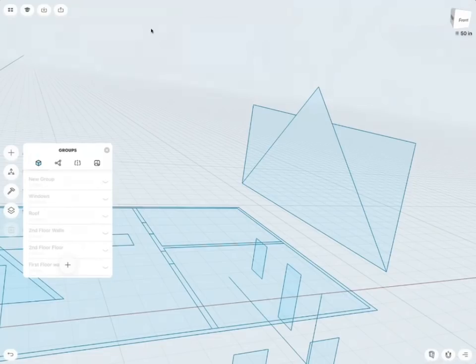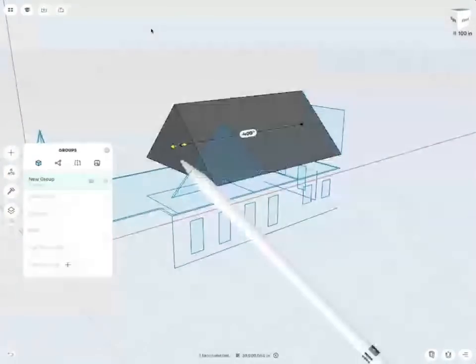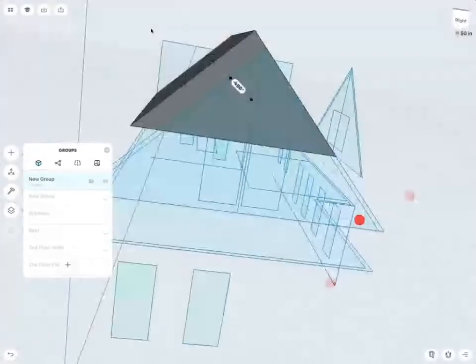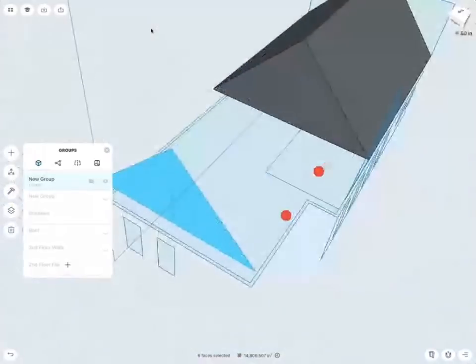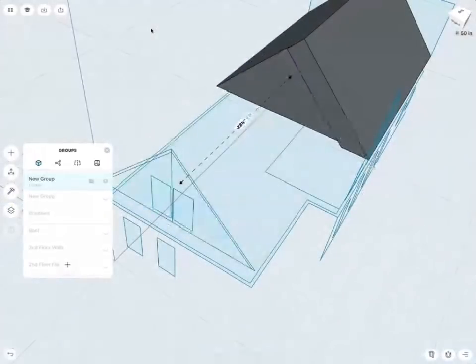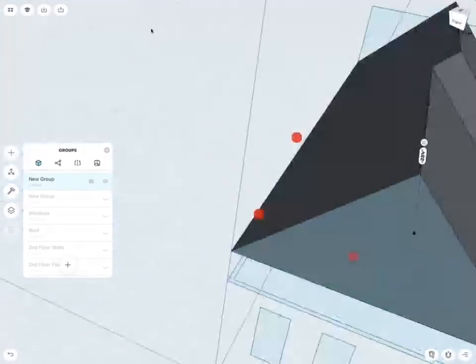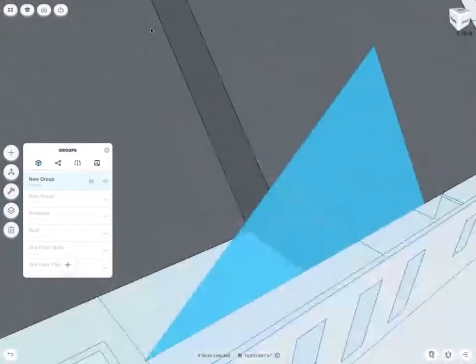So in this case here, I will leave this one as is, so you see what I was talking about. And this face to create the roof, then with the pencil we can extrude out. This was around 400 inches. Then I selected all those elements and extrude it in. And you see once it starts to intersect, it subtracts, and we can click on that icon, and instead of subtract, we say union. That joins it together.